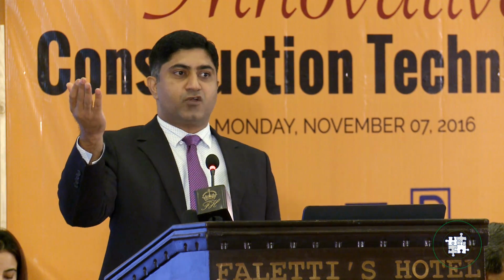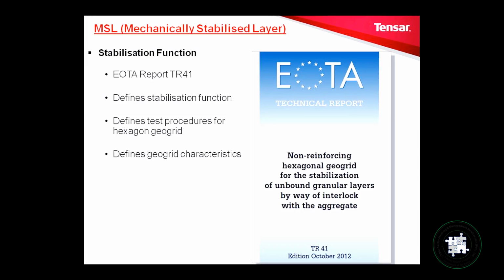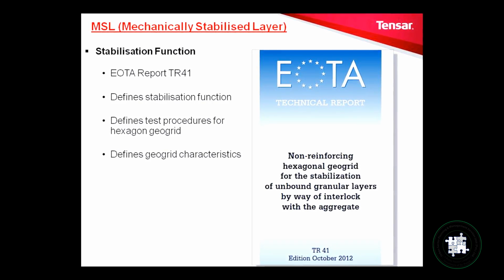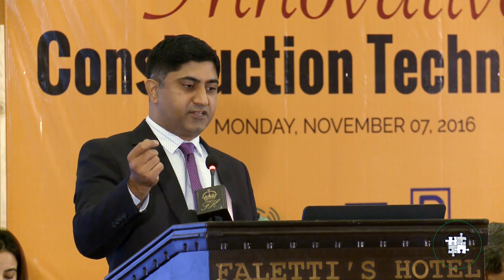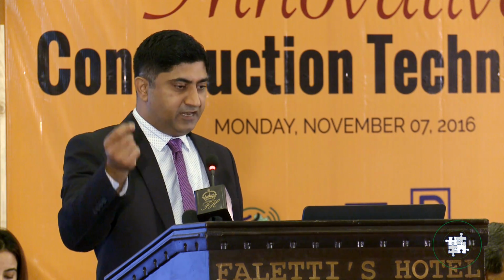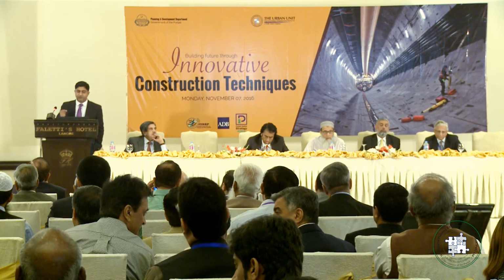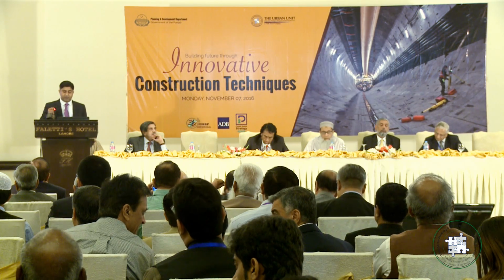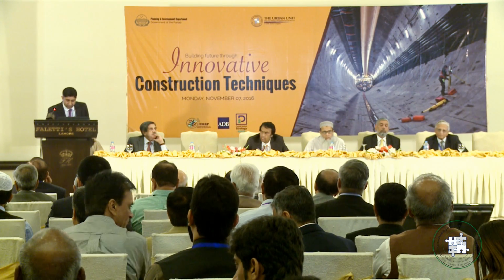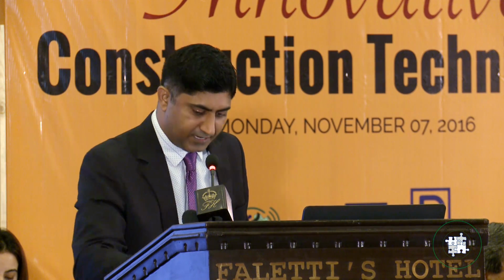So this is a published document. You can get access through the website, Google it, the EOTA report TR41. It defines the stabilization function, it defines MSL, and it defines the test procedure for geo-grid testing. It also offers a distinction between the reinforcement and the stabilization function.